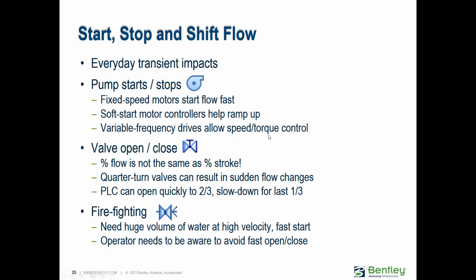For valves, opening and closing. We'll talk a little bit more about this later. I don't want to go into too much detail now, but there are some very complex modeling capabilities when it comes to valves in HAMMER. So it is very important that you take the time to fully understand those capabilities and their assumptions as far as modeling the throttling of a valve, a valve closing or moving to some position. There are a lot of different ways you can do that. So for a normal operating conditions situation, it would just be a matter of how fast that change is happening in the pattern that you set up for that valve, which you assign to the valve.